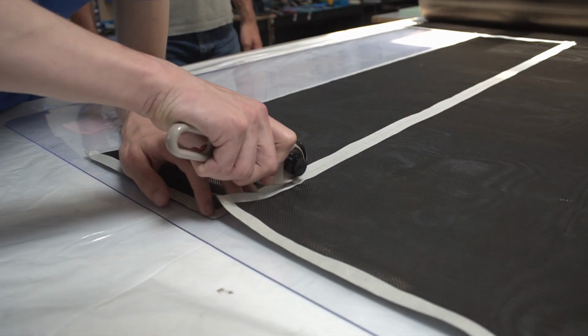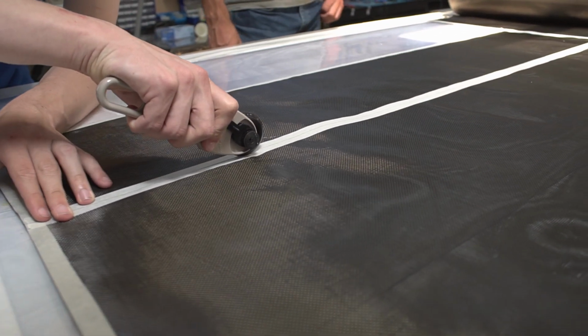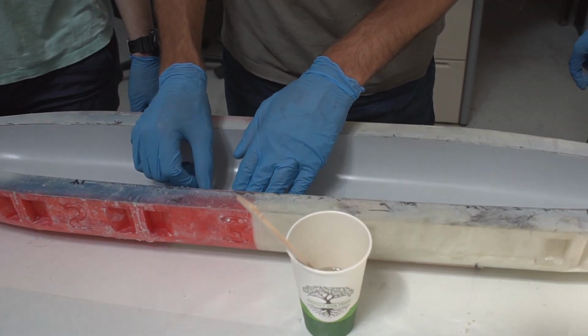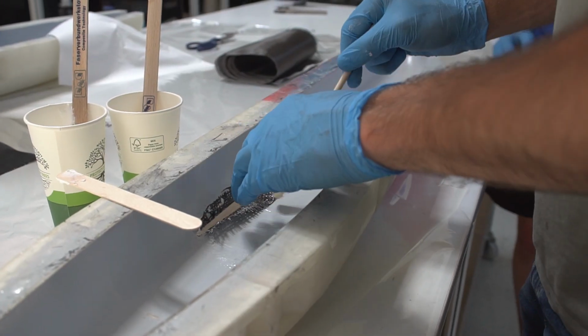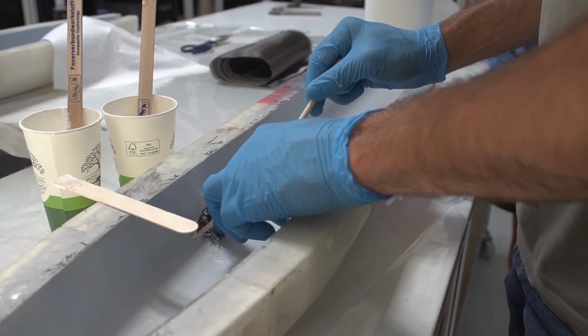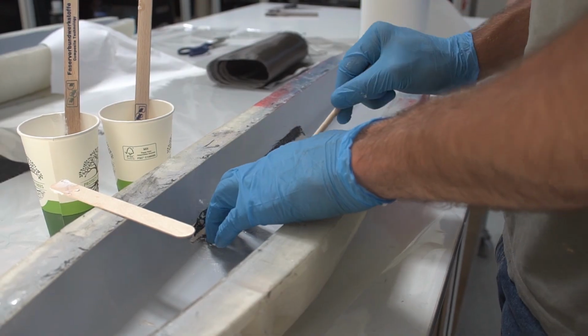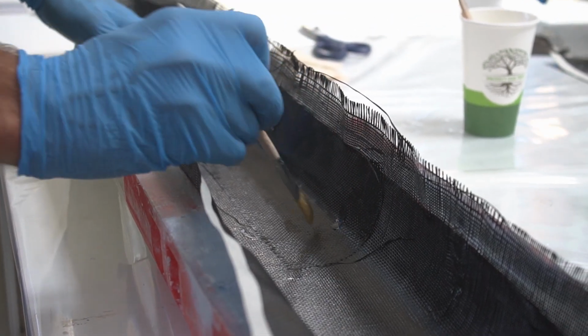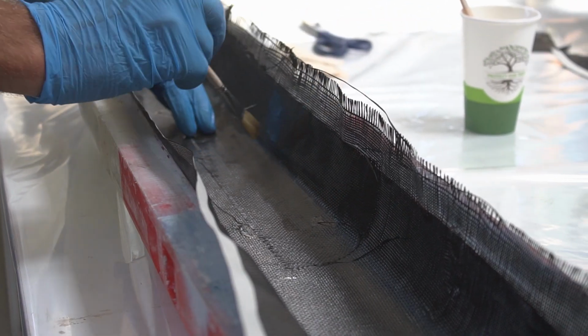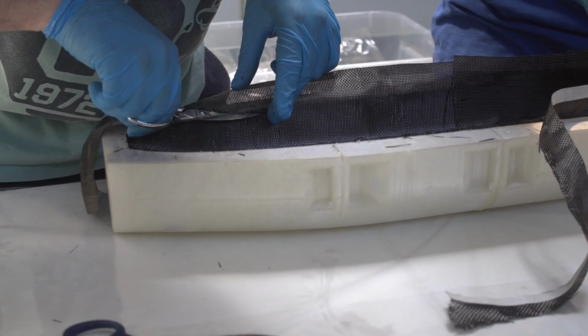We chose to build the fuselage out of carbon and glass fiber. For this, we would need molds, which we printed in segments using our 3D printer. These segments were then glued together, and we used a spray-on putty to cover the uneven surface from the 3D printer. This was then sanded and polished. From these molds, we were able to build many parts, which was great for our prototyping.